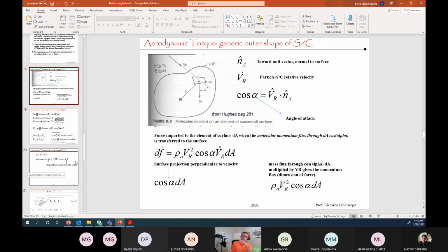Yeah, I would say that it makes things definitely more complicated. If you have an attached one or even a detached one, then the first thought would be that the density of the atmosphere after the shock or shocks, because you may have multiple ones, that you use to formulate the problem, like in this slide, is not going to be just the same rho everywhere. It's going to be different values depending on the location around the spacecraft.